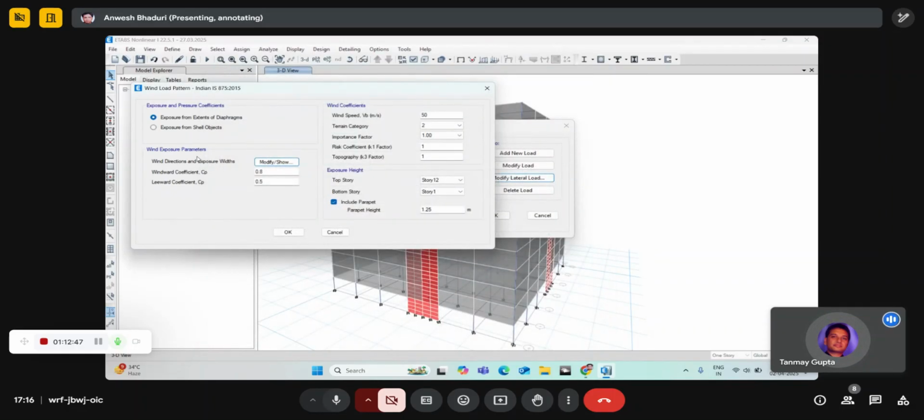If I create a purlin and rafter kind of structure, a support truss structure, will it create cladding in that direction also, say at 30 or 45 degrees? No, that has to be done manually. In that case, we'll need to define a wind load case with the auto lateral load set to none, and define the wind pressure as uniform load on shell or purlin, or as frame load on the purlin. That will be in the individual load definitions, at each purlin.